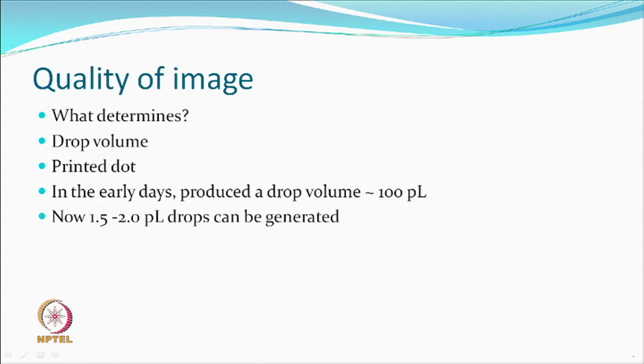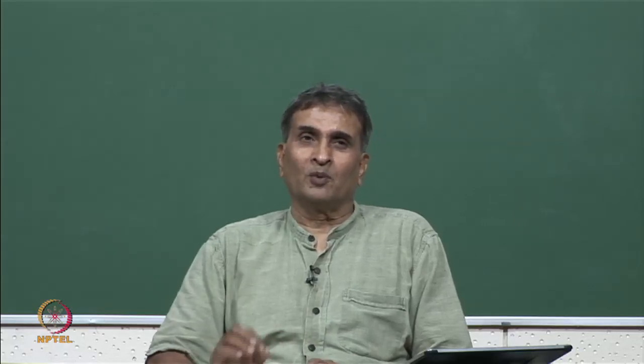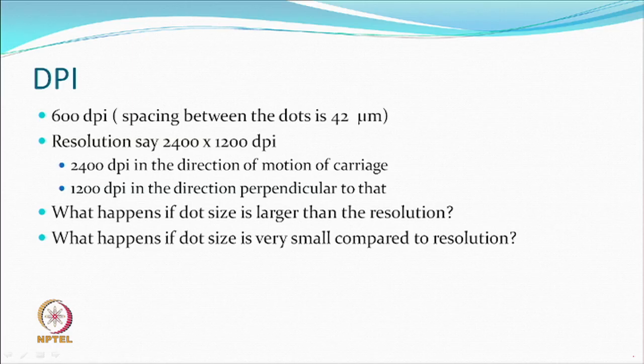But that would also mean that you will have not only a small drop size, but the total number of drops or the points or dots to be printed will also be large. So, the number of nozzles that you may have will also be large, and all of them have to be accommodated. So, we express our resolution in dots per inch.